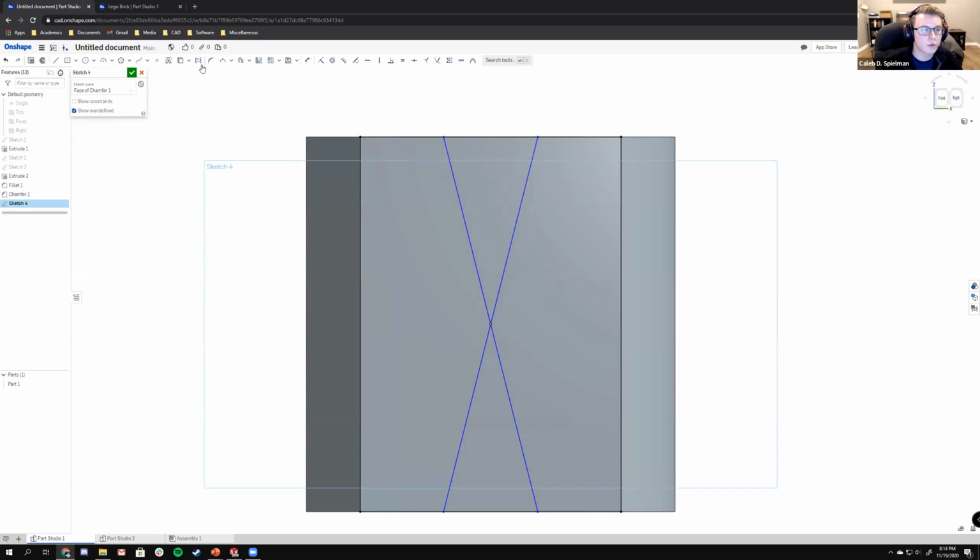Now we're going to go back up to the trim tool, wherever that is. Here's the trim tool. So here, I'm actually going to select the split tool, and I'm going to split these two lines at 4 points, 2 points each. Okay. So now I'm going to just drag these points to be coincident to the others. And it looks like it's not going to auto relate, so I'm just going to do it manually. Coincident is right here. Just going to select those. Very good.